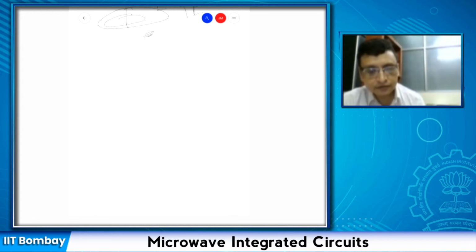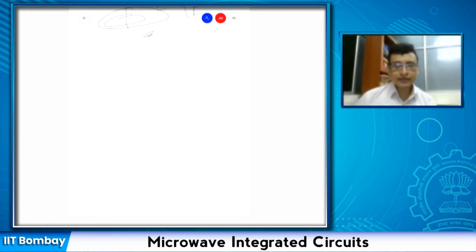Okay. So is there any bouncing plane wave phenomenon going on in the TM mode for a parallel plate waveguide? No, there is no bouncing. It's just that multiple waves exist. When I say TE mode, it is one electromagnetic wave. When I say TM mode, it is another electromagnetic wave. If I say that a parallel plate waveguide has solutions for all three, that is TEM, TE, and TM, it means all three types of waves coexist and they transmit together. That's what it means. So the power transmission is a result of all the three modes existing inside the waveguide. So these are not theoretical concepts, these are actual waves. You can filter out one from the other.